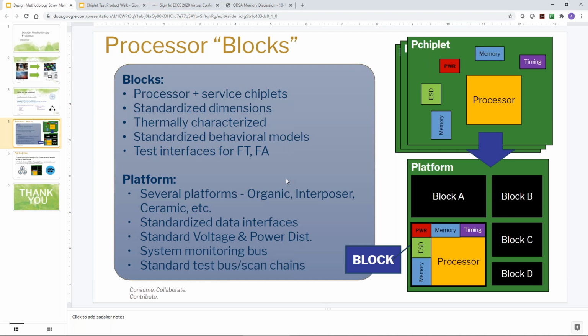So my idea was that by giving the processor its services right next to it, pre-developed, predefined, and pre-designed, you reduce a lot of that co-design. Now you can really just plop down blocks and decide their signal connectivity, and that way you can experiment with architectures in rapid fire. If you have something that works really well and everybody wants to buy, you can always go back and redesign with centralized power distribution and optimizing for memory and so on.